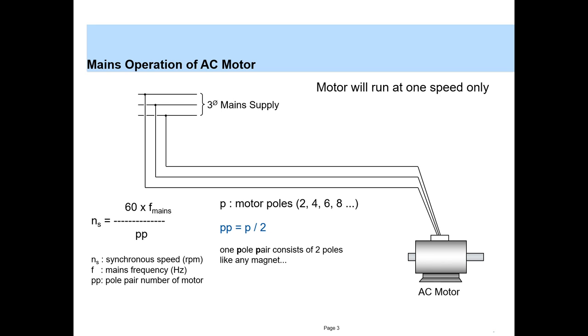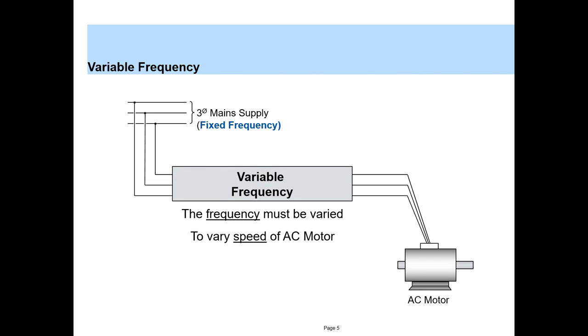And also you are extracting extra energy or power, because your motor will need more power to run at 1500 rpm. So if you are somehow able to run the motor at 800 rpm, this motor will consume less energy, right? And this will result in power savings and operating cost savings as well. So how do you achieve that? Use a drive, a variable frequency drive.